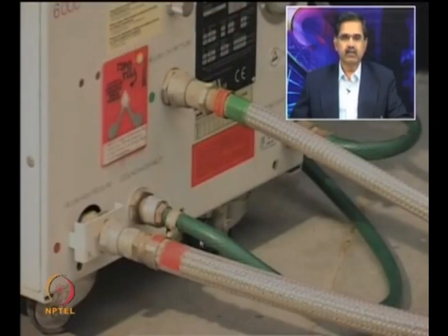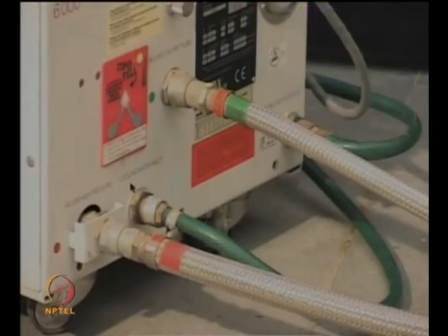Now, what you also see from here is a water cooling arrangement. The water will go in as inlet and come out as outlet from this. It will go to the chiller, and again the water will enter from this place. The cold water will take the heat of compression from this place. It will enter, take the heat of compression, and come out as hot water from this, and it will again go back to the chiller and come back again from this particular port.